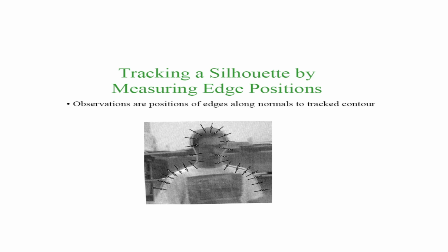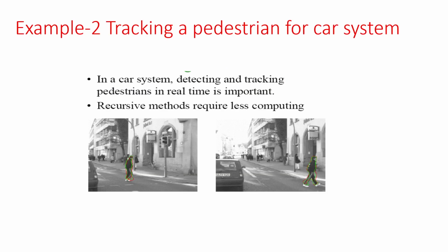So, say this is a typical face tracking system using a simple monocular camera. The positions of the edges are marked, and the person, the pedestrian or whatever, is moving. His motion is getting tracked using the camera, and the resultant tracking algorithm is telling you the x position, x velocity, y position, y velocity, everything. This is a typical ADAS scenario. A crossing pedestrian is moving, this fellow is just crossing the road, and the vehicle has, say, just a camera.